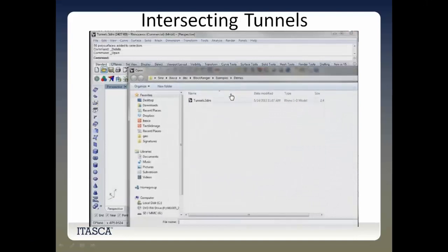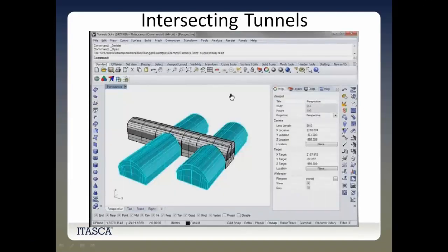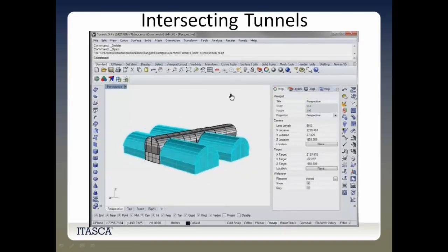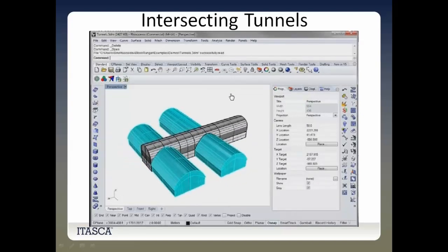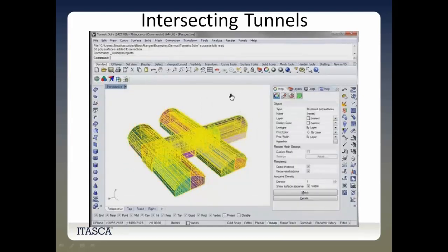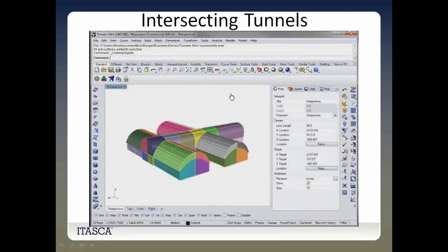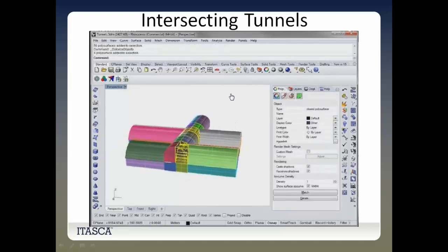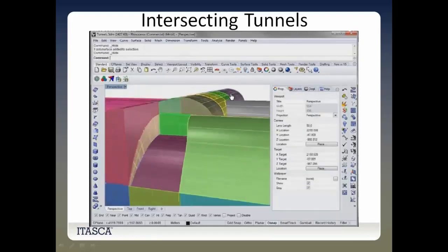This is an example of a civil tunnel. I'm not going into the whole details, but I want to show you the block layout. Again, I created this solid. These blocks obviously have to respect the requirements, meaning that each face has to match another face. So you can see there is some work that goes into that. That's not automatic. The number of blocks is somewhere in the order of 40, 50. And when you go past 1,000 blocks, it becomes extremely tedious.